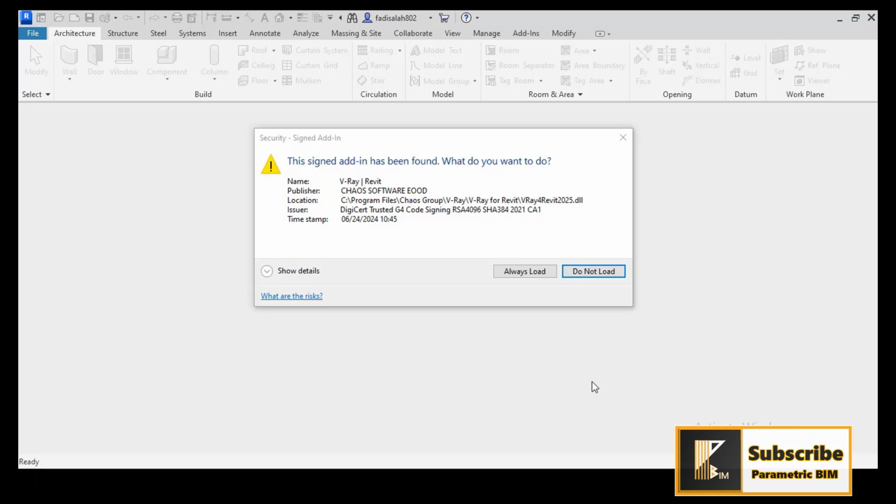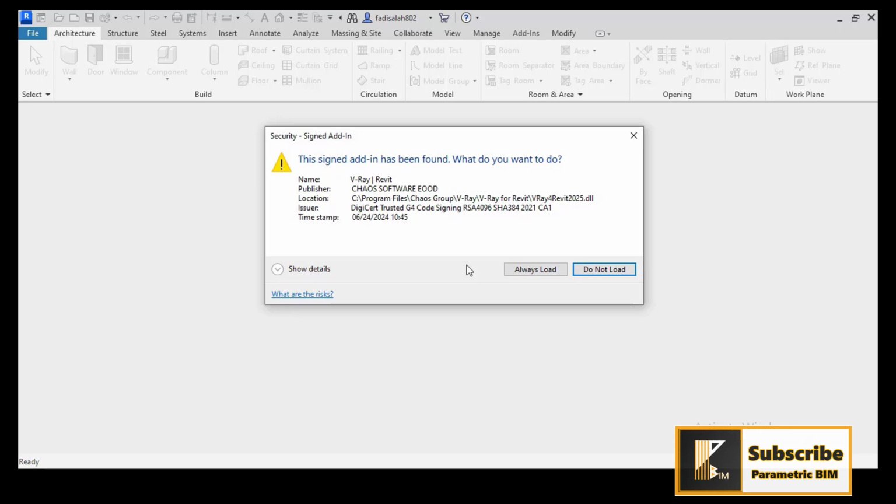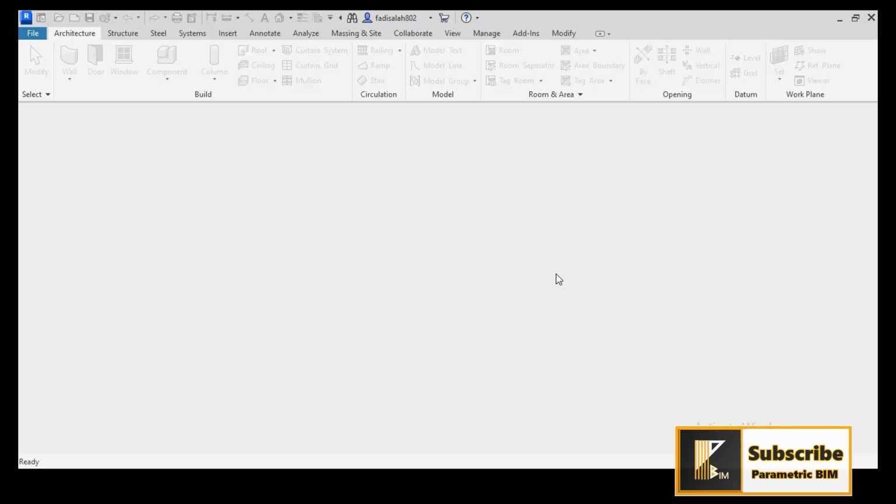Once you open Revit for the first time after you install Vray, it will ask you if you want to load the plugin or not. So this message will appear to you: this signed add-in has been found. What do you want to do? I will go with the option of always load, and this way it will load the plugin to the add-ins of the Revit program. So as you see here, the Vray was added to the tabs here.